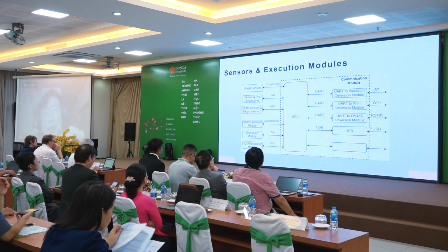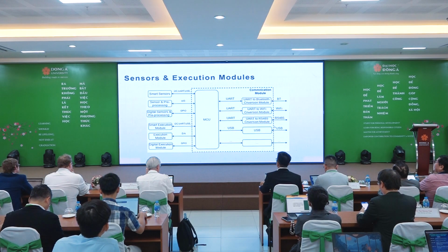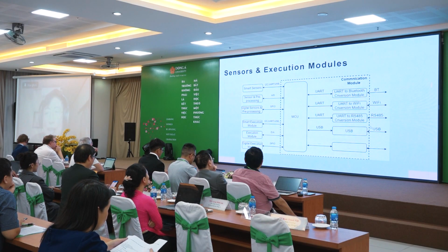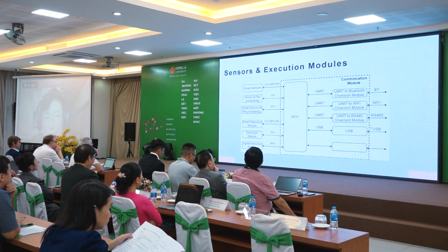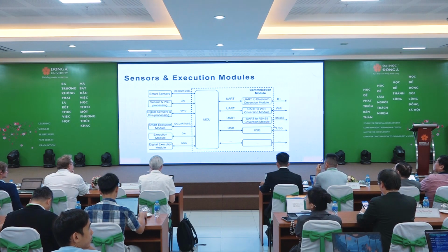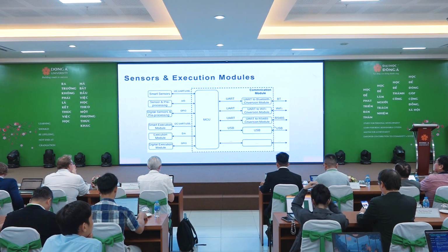This is the sensor execution module, the usual implementation. Starting from the 80s, we have been using a microcontroller. There is connectivity to smart sensors, meaning the sensor can connect to the MCU through I2C, UART, USB, etc. We also have analog sensors, so there is pre-processing and AD conversion, and then digital sensors controlled by GPIO.